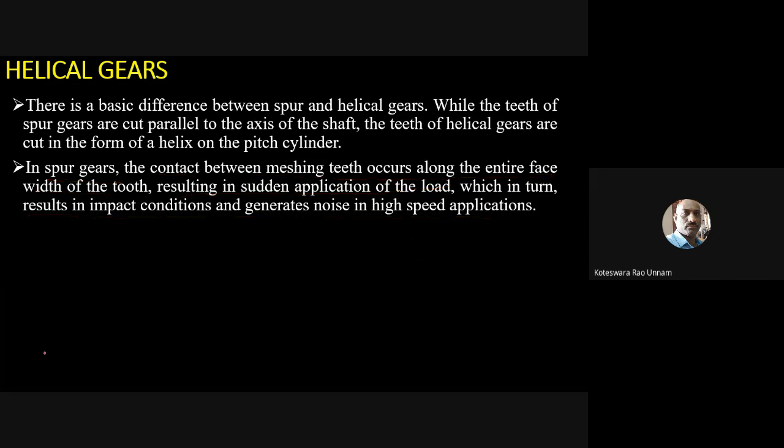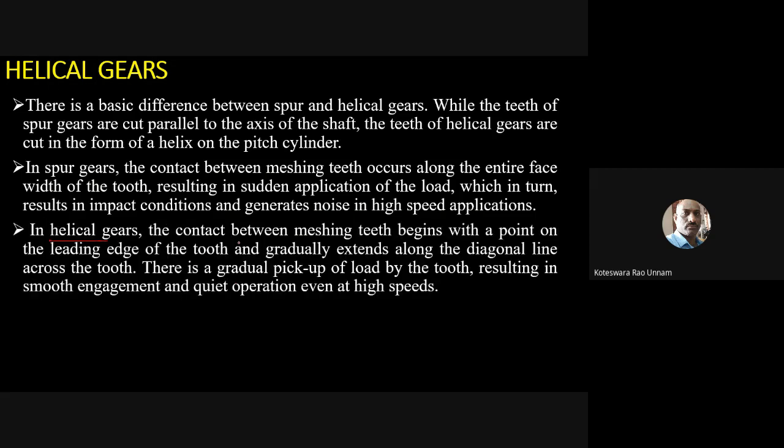Whereas in the case of helical gears, the contact is gradual and also progressive. In helical gears, the contact between meshing teeth begins at a point on the leading edge of the tooth and gradually extends to diagonal lines across the tooth. There is a gradual pickup of the load by the tooth, resulting in smooth engagement and quiet operation even at high speed.